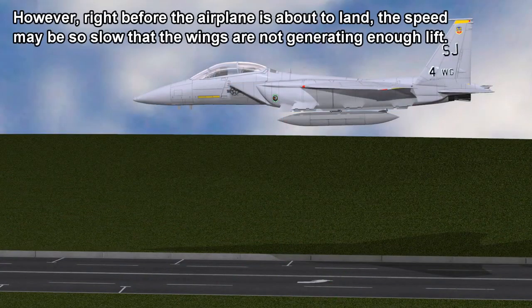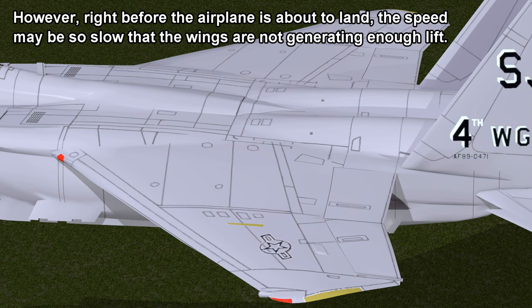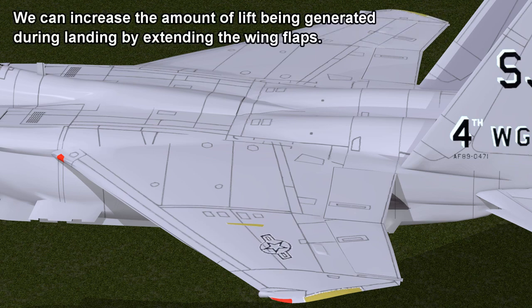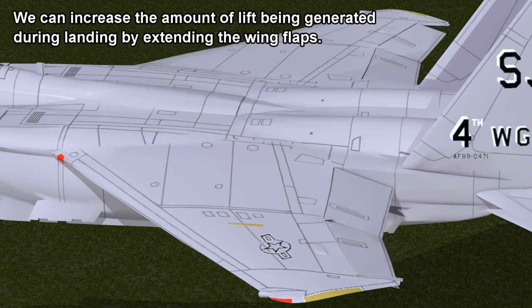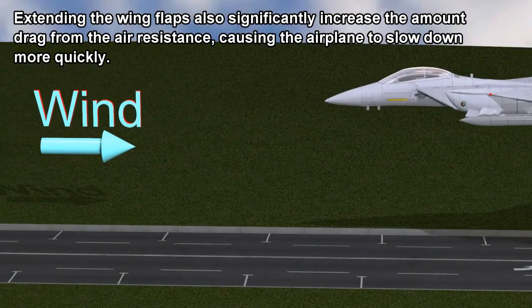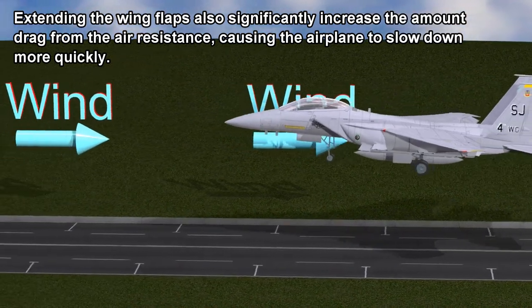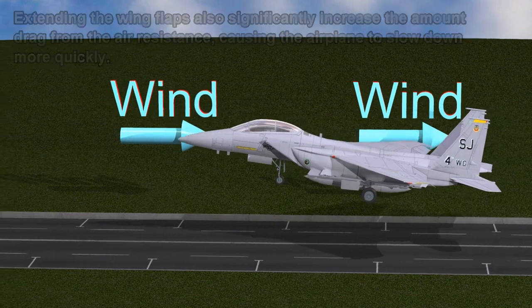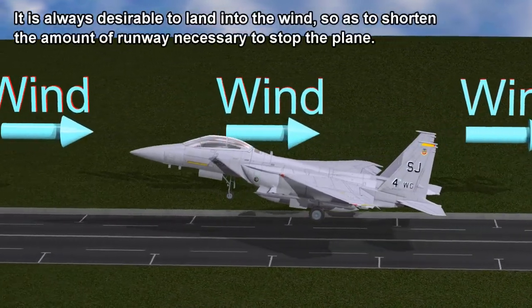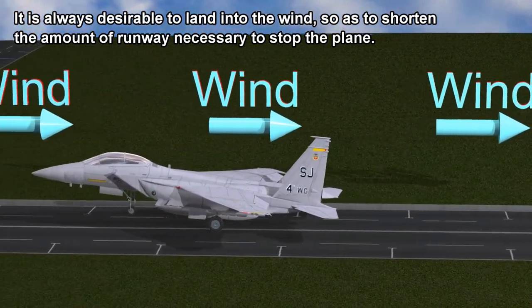However, right before the airplane is about to land, the speed may be so slow that the wings are not generating enough lift. We can increase the amount of lift being generated during landing by extending the wing flaps. Extending the wing flaps also significantly increases the amount of drag from the air resistance, causing the airplane to slow down more quickly. It's always desirable to land into the wind, so as to shorten the amount of runway necessary to stop the plane.